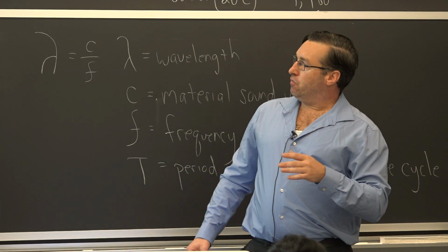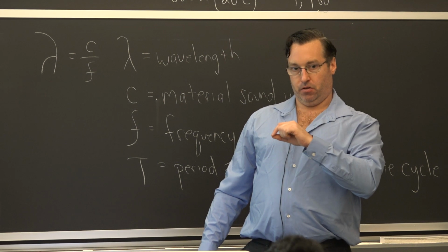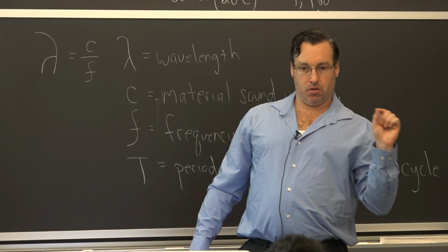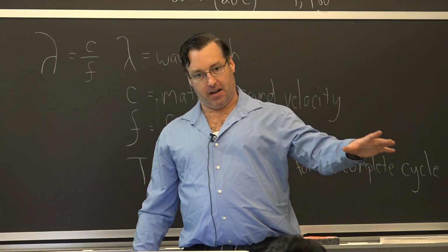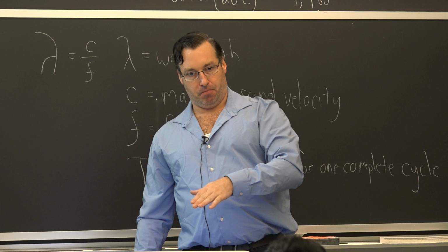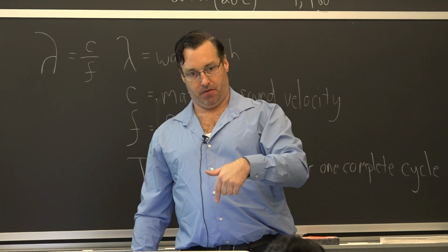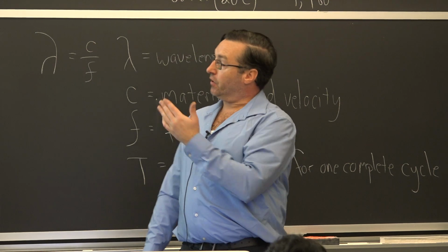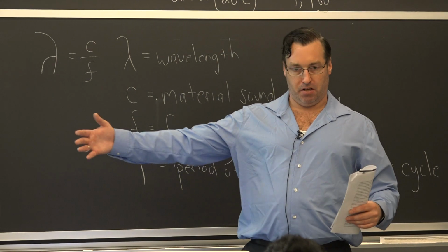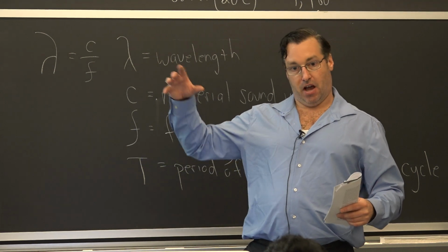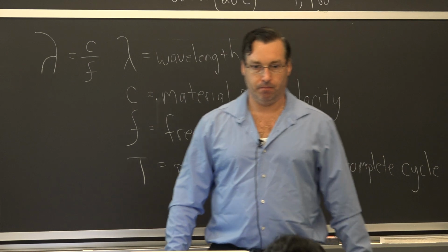What you would do with that is use the eddy current technique for metals to find those very small flaw sizes. But the trade-off is you cannot penetrate deep into the sample. You can only go 1 to 2 millimeters depth from the surface. With ultrasonics, it's essentially the opposite. You can go very deep into the sample because it's operating on the acoustic spectrum rather than the electromagnetic spectrum.